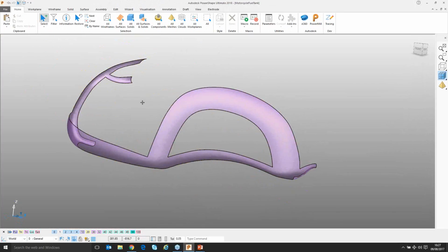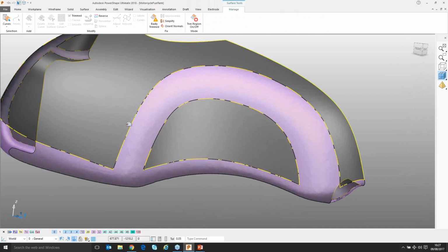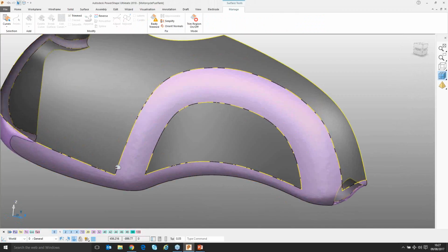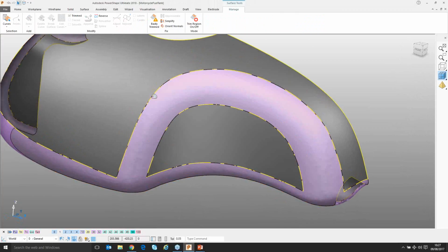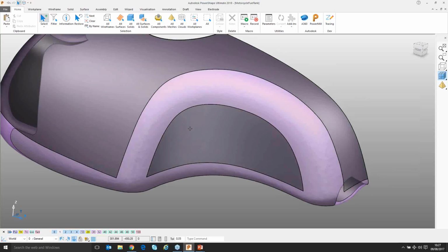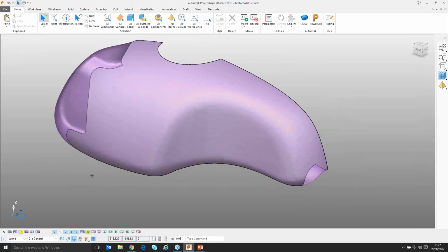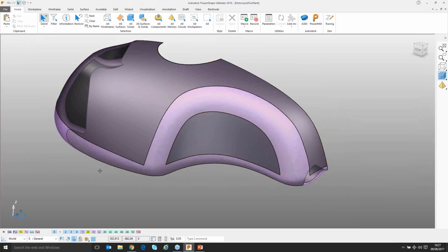I won't use that because I don't want the edges here to confuse when I fit the surface, effectively which edge of the surface of the triangles I'm trying to use and which direction the tangency goes off the triangles. So what I'll use is the original before I limited, on this page here. So just to be clear, what I've got is the original triangle set without any limiting, and I've got those new surfaces that I created.